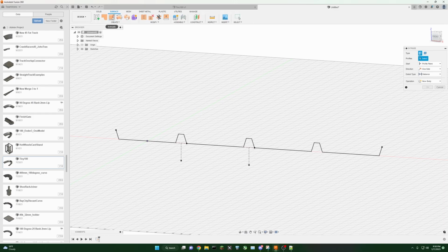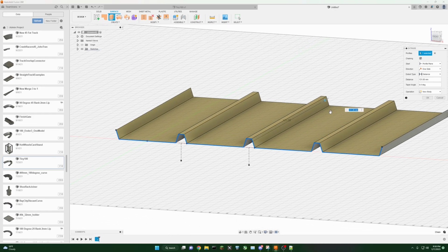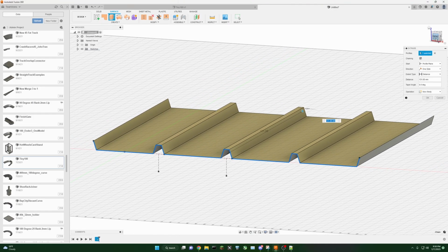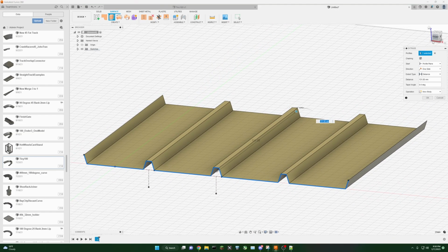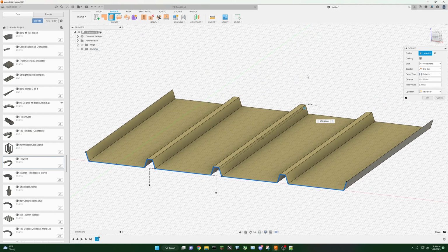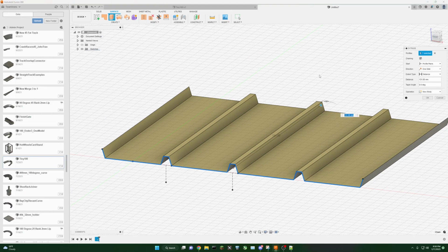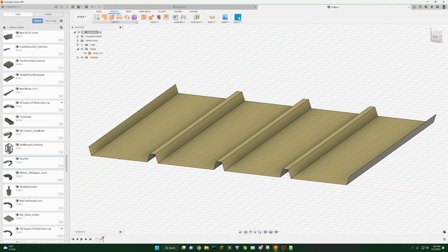And if you're in the Surface tab and you click Extrude, you'll find that you're able to extrude these thin things, right? So it's important to know that these don't have any actual thickness to them. And so there'll be extra steps that you have to do. But if you find that you're in this position, and you've already created this body, it's not really a body, it's a surface body, there is a tool to thicken these, and it is hidden.